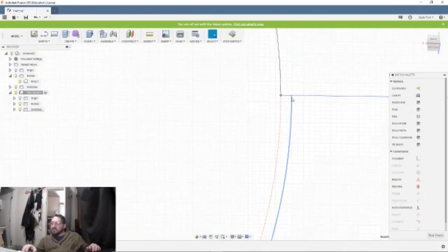Triple click on that line. Any of those. Wait, did you say triple click? Yep. Yeah, so they're not linked. If you triple click it, the whole outline should select. Something's not linked there. Something's not closed.